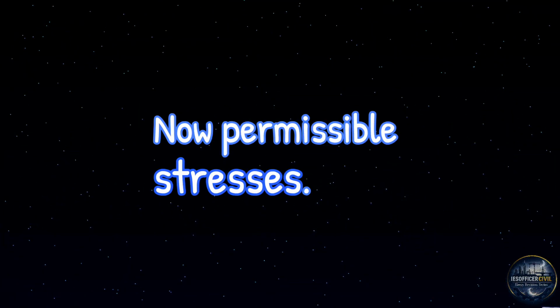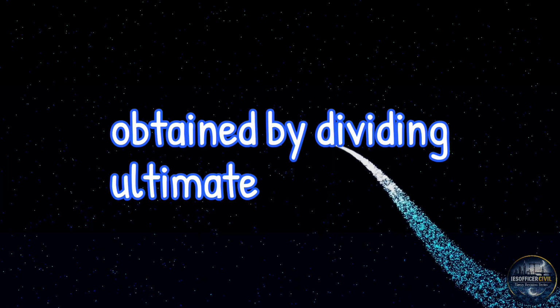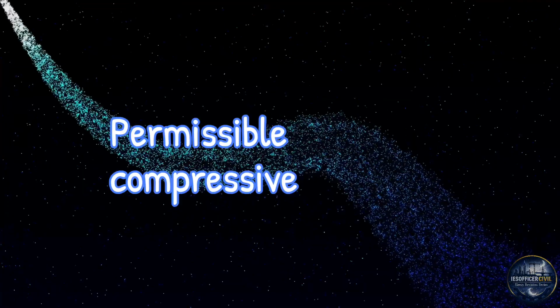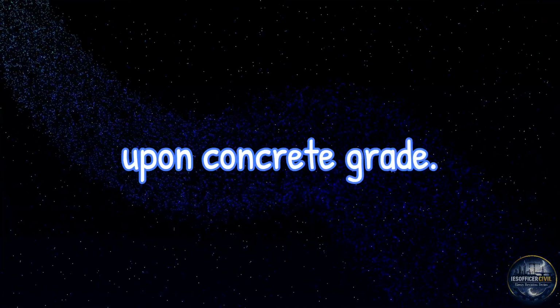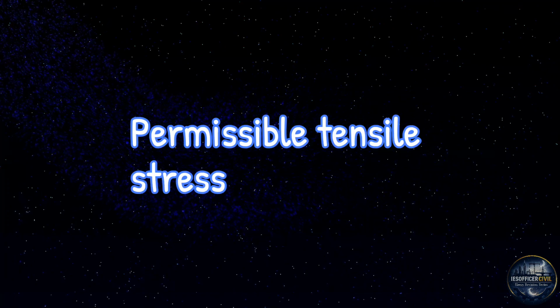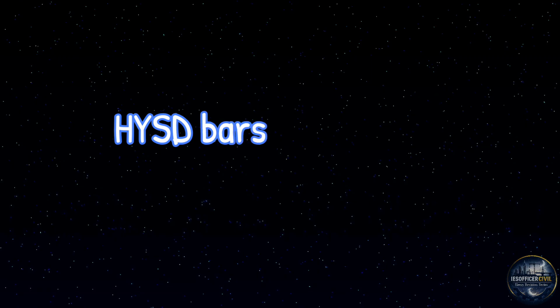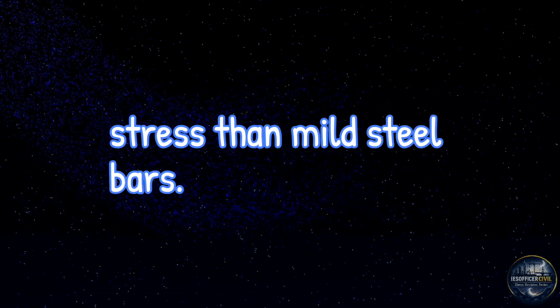Now permissible stresses. Permissible stresses are obtained by dividing ultimate stresses with factor of safety. Permissible compressive stress in concrete depends upon concrete grade. Permissible tensile stress in steel depends upon steel grade. HYSD bars allow higher permissible stress than mild steel bars.